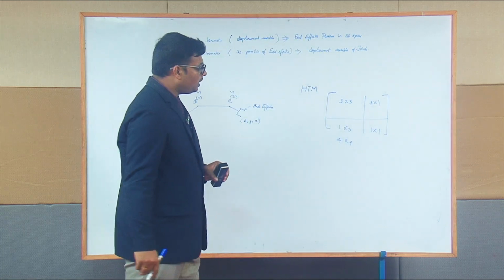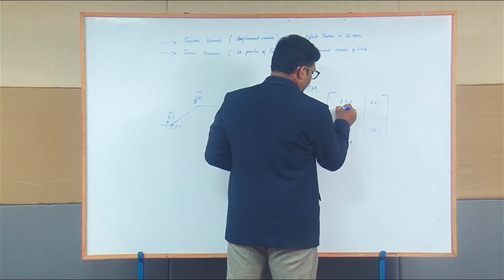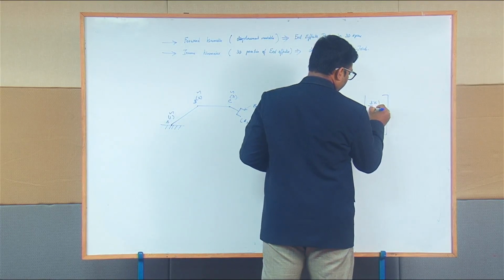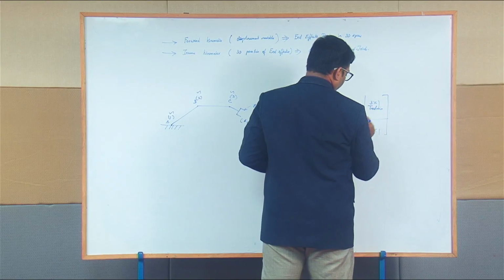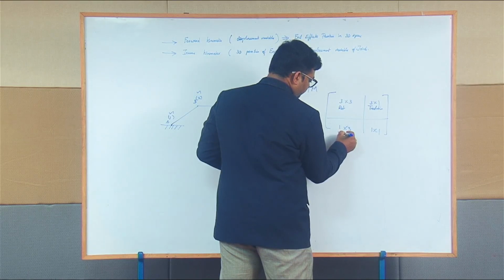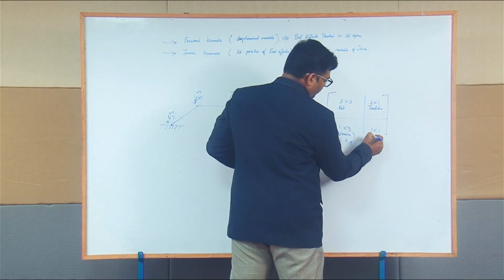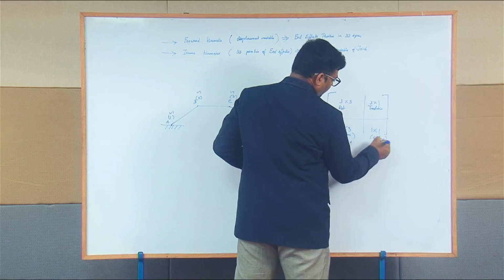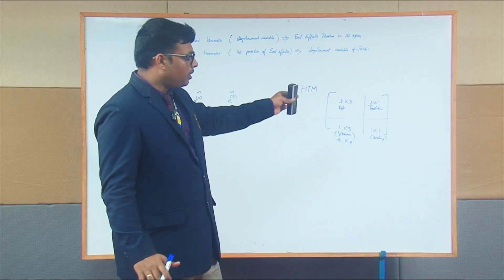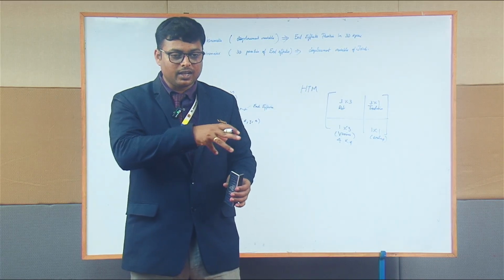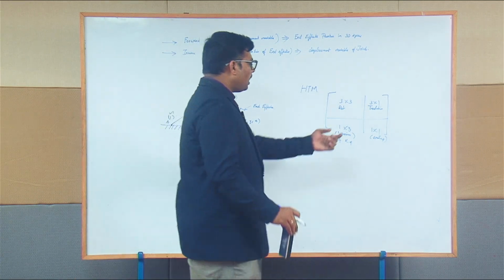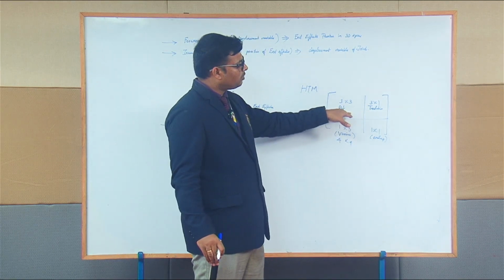The 3 cross 3 gives me the rotation, or we say the rotational matrix. This we call translational, or linear movement. This is for the perspective of vision, and this is for scaling. So a homogeneous transformation matrix contains all these phenomena with respect to the end effector's rotation and translation, followed by vision and scaling factor. Preferably, we will understand this matrix with respect to rotation and translation.